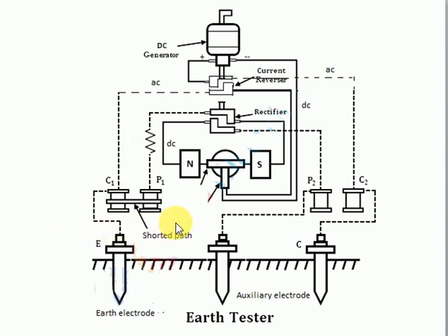And you already know why it should be low. It should be very less. If it is showing some other value, like more than 10, then we cannot connect the earthing point to this ground. And we have taken three sets of readings. We can change the position of these two electrodes in the same line, at the same distance, with a different angle to get the three sets of readings. If we take the average, we can get the earthing resistance of that.